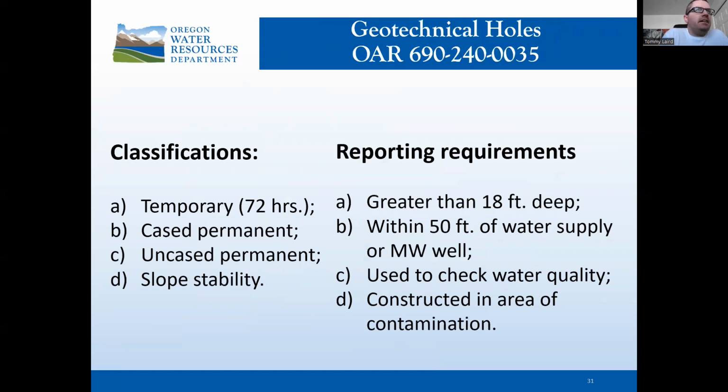So quickly, additional classification for geotechnical holes. This can be found in OAR 690-240-0035. Classification is that they are temporary. They shall not be there for more than 72 hours. They can be cased permanently or uncased permanent, and they can be done for slope stability.